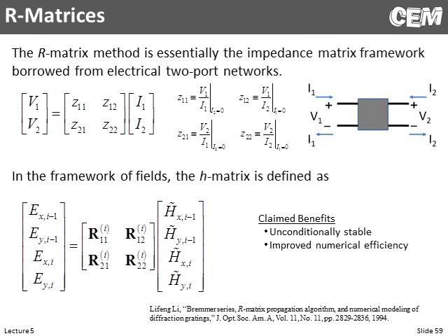And another one you may see is R matrices, which relates currents to voltages. And also argued to be unconditionally stable with improved numerical efficiency. I do believe it's stable. The jury's out on the numerical efficiency. I'd have to try it myself to really say, yep, it's better.